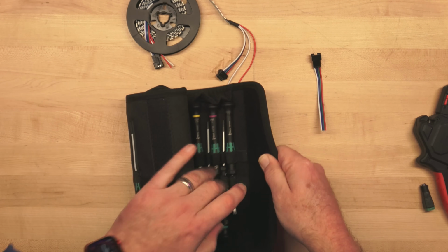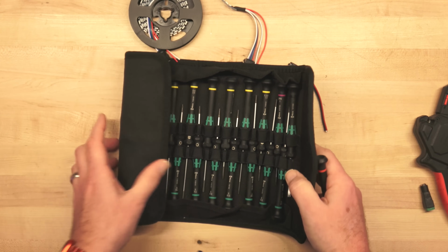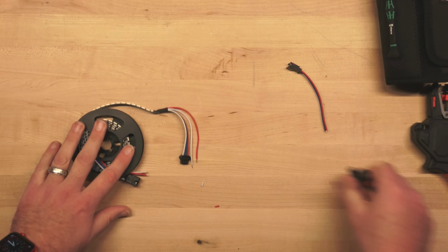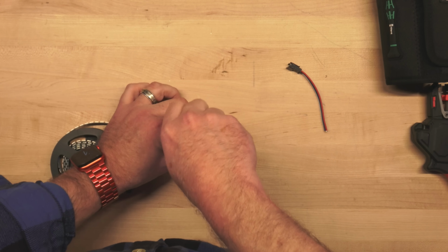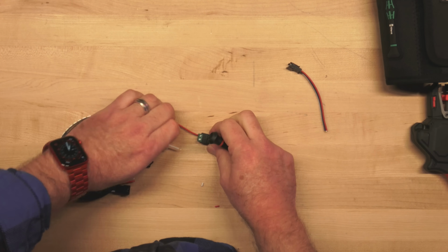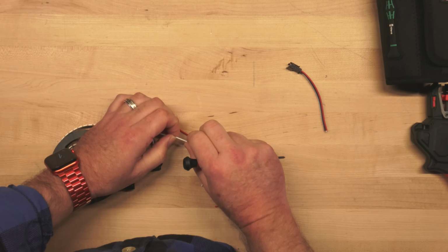Now, strips normally come in 3 primary flavors: 5 volt, 12 volts, or 24 volts. It doesn't matter which one you have as long as your power brick outputs the correct matching voltage and that the ground, but not the power, is shared between the module and the strip. And so let's connect the module.